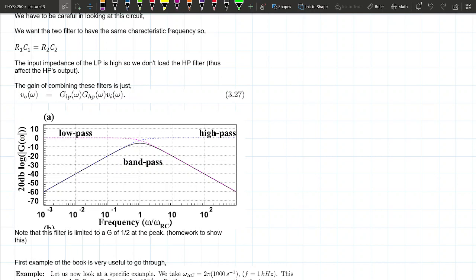The blue is basically the first half, but then if you send that signal into a low pass filter, you filter out the high end also, and you end up with the stuff just in the middle. There is a price for this. Instead of getting a gain of 1, guess what this gain here is? Yeah, it's about half. But if you don't have an inductor, that's what you get to deal with.